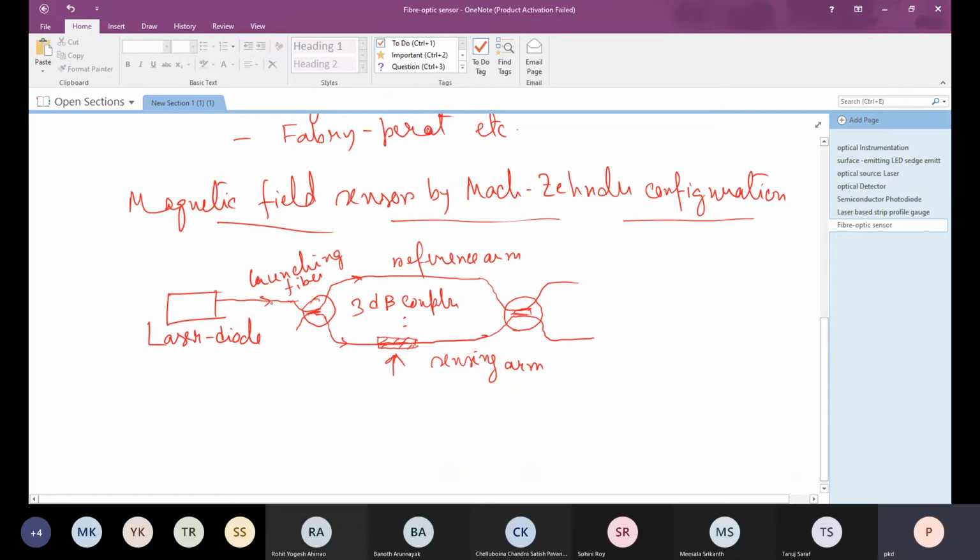So if I am at 630 nanometer, or 0.6 micron, it has to be 0.5 or 0.4 micron close. Usually these two surfaces are polished and put side by side through a gel, and depending on the length of this, the percentage coupled changes.